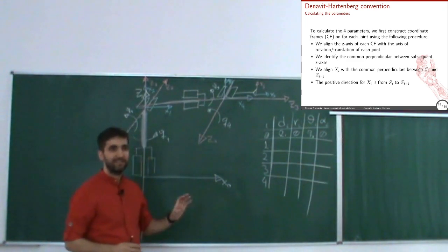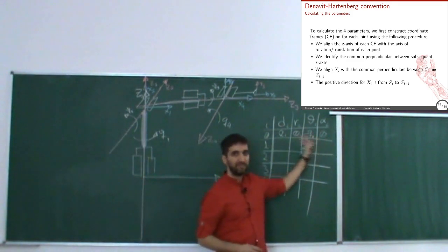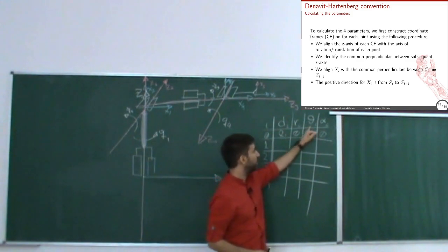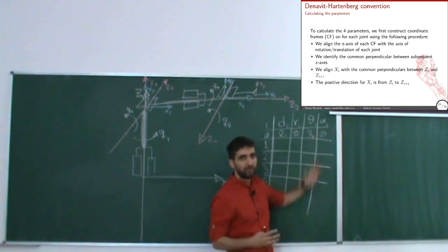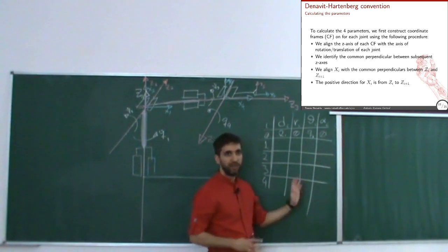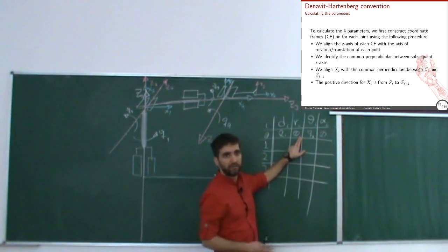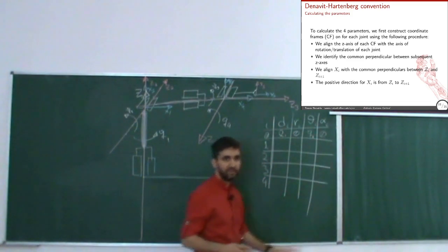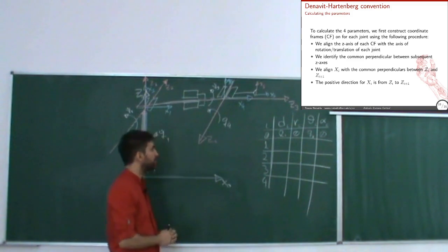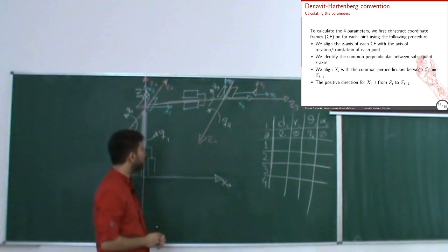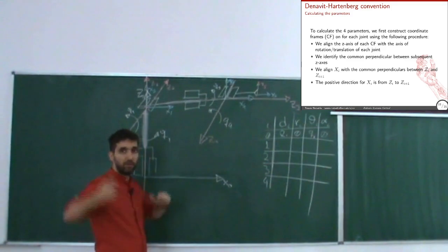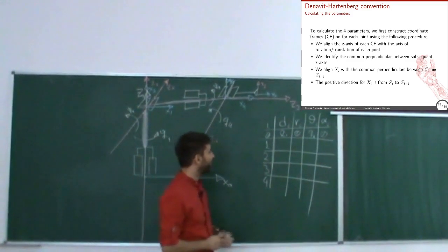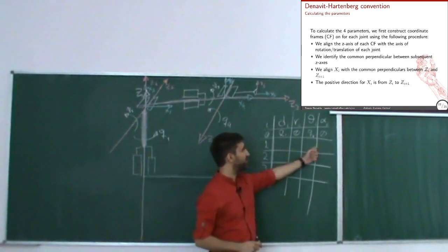Okay. So that's how we define the things. You see that this distance here is actually a length, and this angle here is actually an angle. Okay, so things make sense. Make sure you double check this. Don't put me here like an angle 30 degrees or 90 degrees or something, because these are distances, these are angles. Okay? That's also like a sanity check to realize if things are going fine or not. Good, so we finished with the first joint after 20 minutes. It's gonna go faster. Let's go with the second joint.